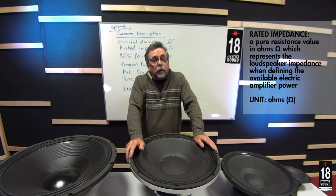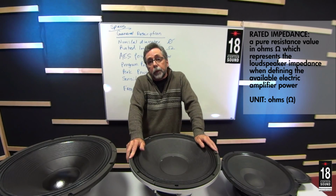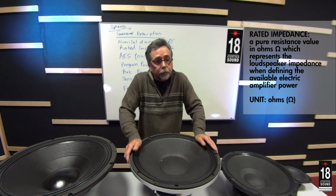The connection between 8 and 4 is that 2 8 ohm speakers could be put in parallel to work as a 4 ohm load to an amplifier, 2 4 ohm speakers in series to be an 8 ohm load to an amplifier, and so on.